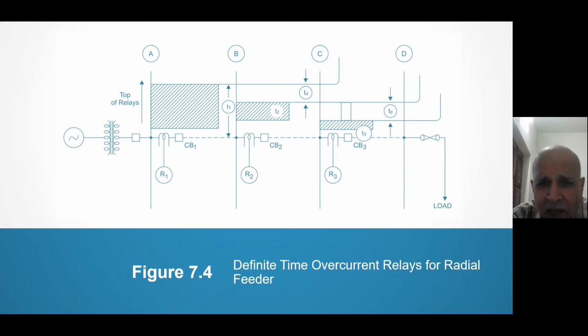But then, my dear friends, the problem is, if you can appreciate the problem, a very big problem has occurred. In the first zone AB, which has the fault, if fault occurs in AB, it is the worst fault because it is very near to the generator. The time taken is 0.6 seconds. And within that, there can be very bad damage.